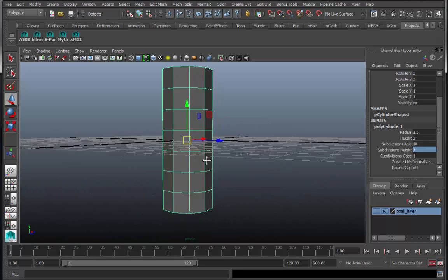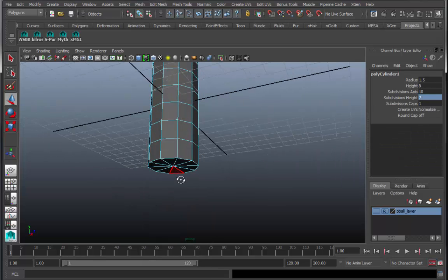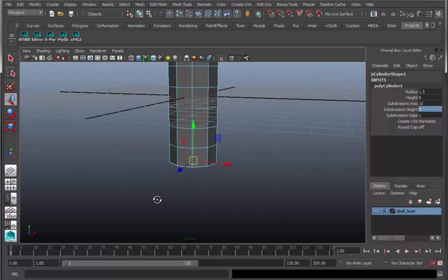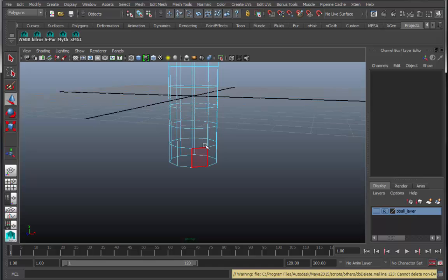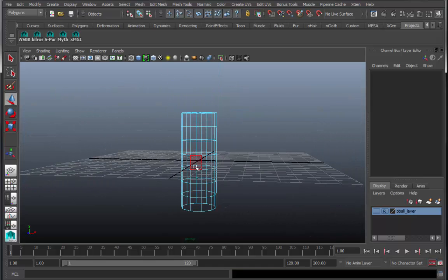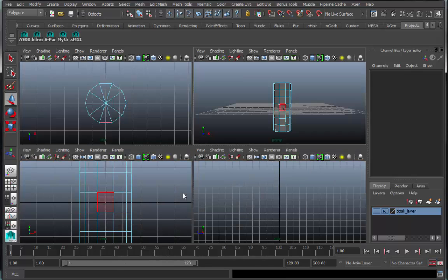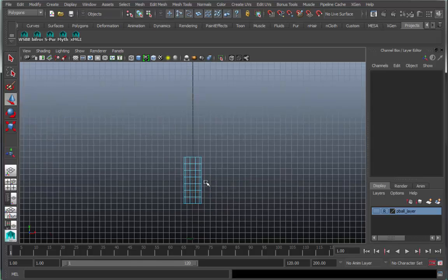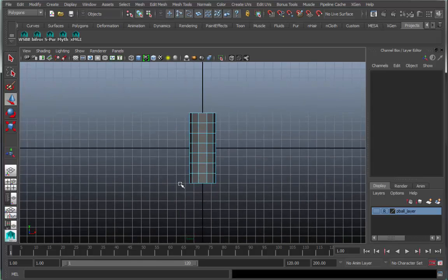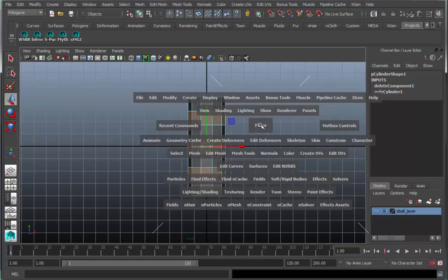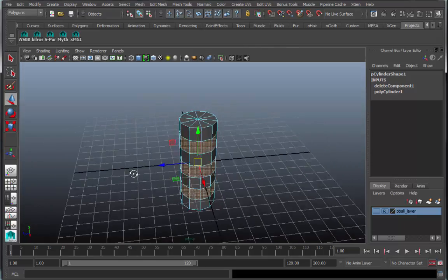So getting in close and personal on this, I want to have everyone grab the faces on the bottom. And I'm doing the old select unselect trick. Make sure it's there, and I delete. But what we're going to do in this particular case is we're going to grab the ringlets, the odd numbered ringlets of the polygons of this cylinder, like so. There will be 3 sets. Here's the first, the second, and the third. So what I have is a buffer of unselected polygon rings at the top and bottom. It's probably a little more obvious in the perspective mode.